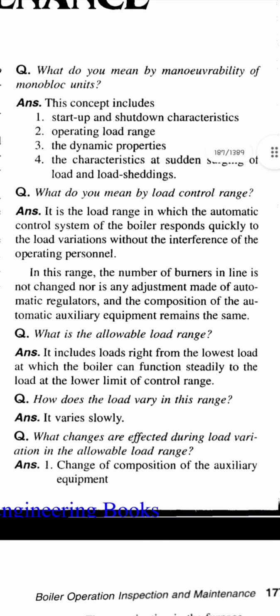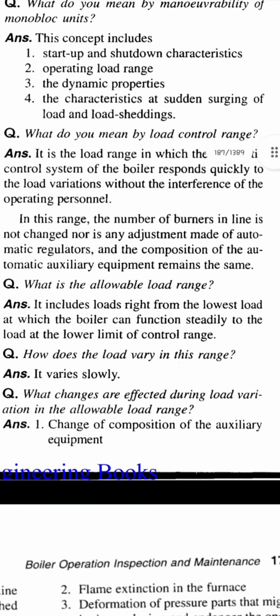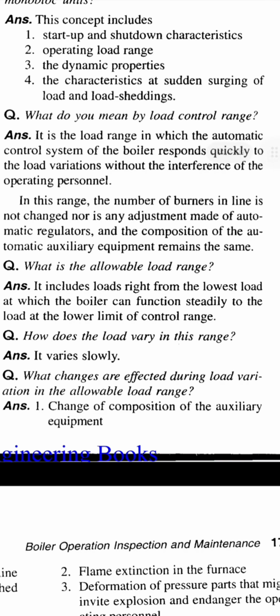Question, what do you mean by maneuverability of monoblock unit? Answer, the concept includes startup and shutdown characteristics, operating load range, the dynamic properties, the characteristics at sudden surging of load and load sheddings. Question, what do you mean by load control range?